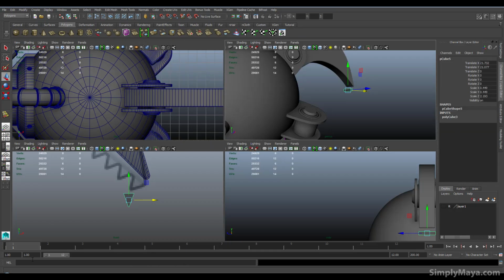particular script, you simply put it in your Maya scripts folder. Now, depending on your OS, that could be in different places. If you're on a Windows system, then you'll want to put it into your Maya scripts folder, which is normally My Documents, Maya, your version number, and then scripts. On Linux, it's in the home folder in pretty much the same place. Mac, same thing. So you might need to look up where to put your scripts. But once you've got it installed, basically you just download it, take the script and plonk it in the scripts folder. You may have to restart Maya, so that's one thing to keep in mind.